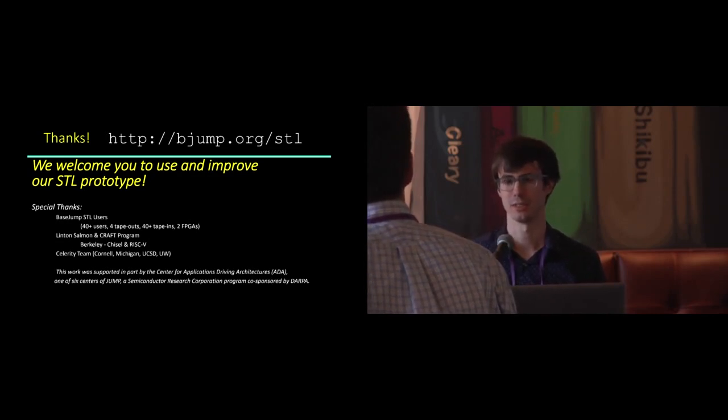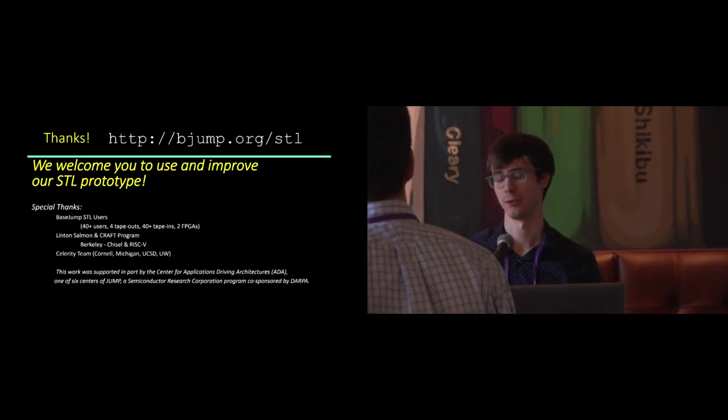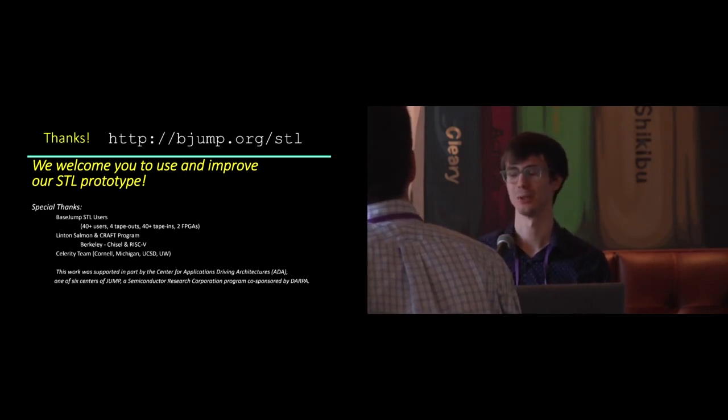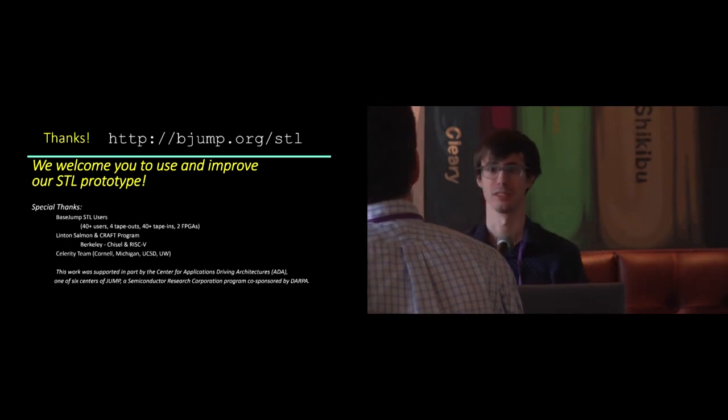We actually use an interesting flow. If you go to Bespoke Silicon Group on GitHub, you can see this SV to V converter, which allows you to convert the sophisticated SystemVerilog to regular Verilog. Unfortunately, using Synopsys Design Compiler is an intermediate, but this will let you feed it into open source tools like Yosys. And that's what we use for open source synthesis.